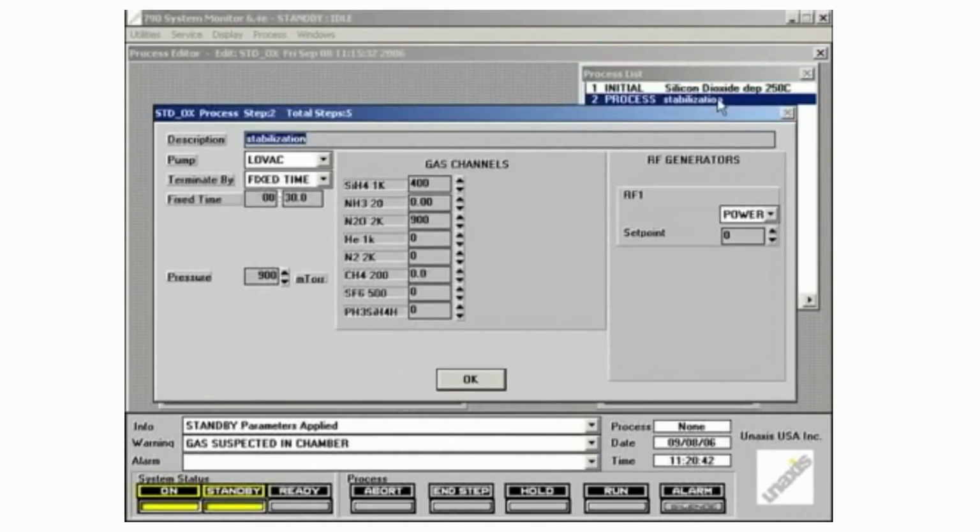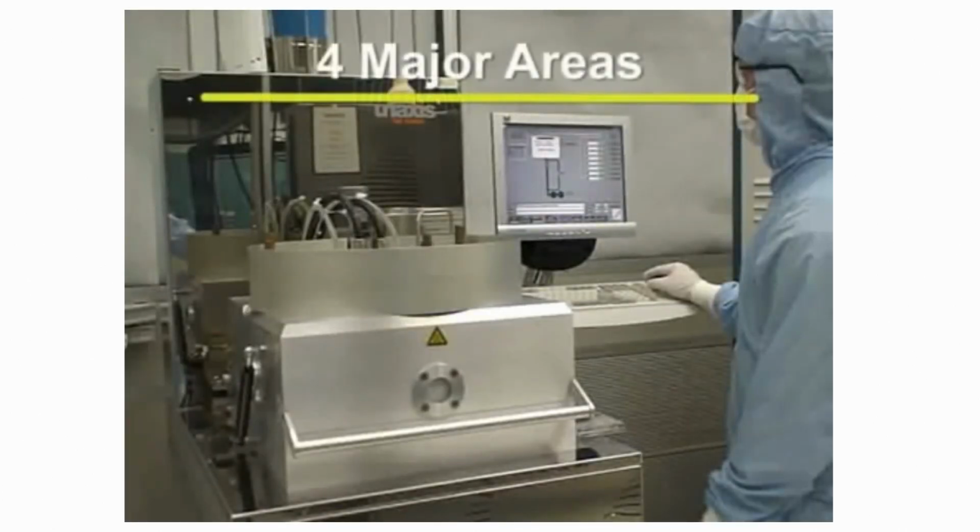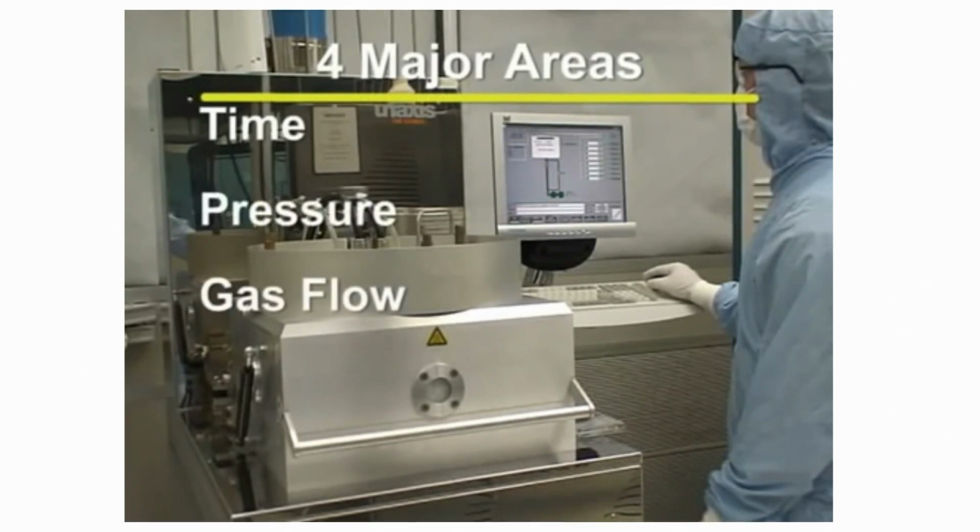This step stabilizes the gas flow rate and sets the process pressure. Because the RF power is off, no processing will actually take place during this step. The process step dialog box has 4 major areas: time, pressure, gas flow, and power.